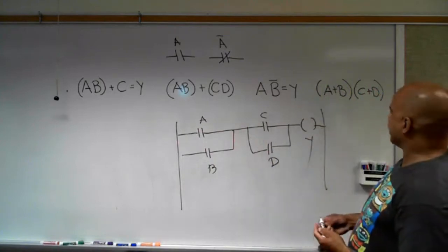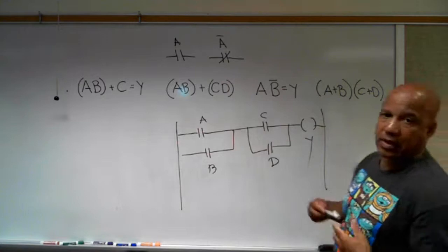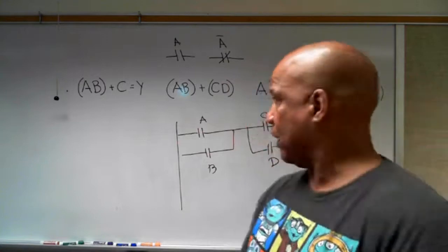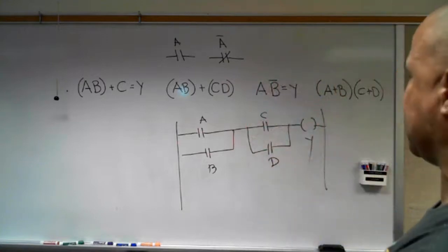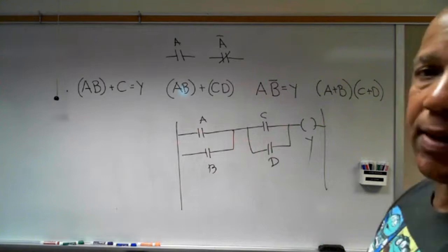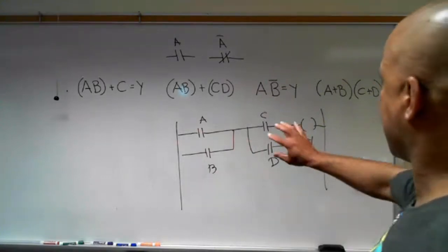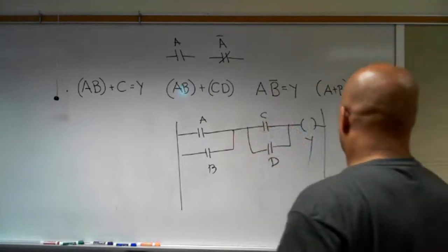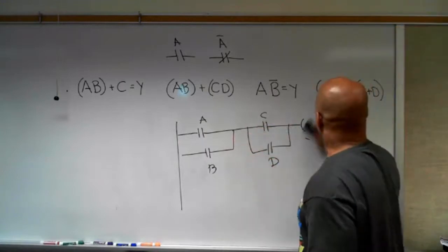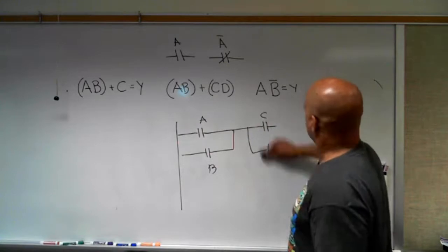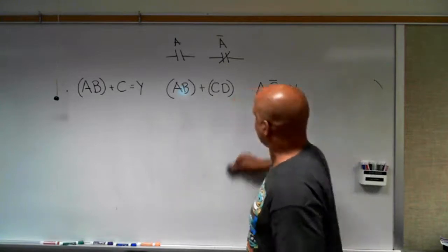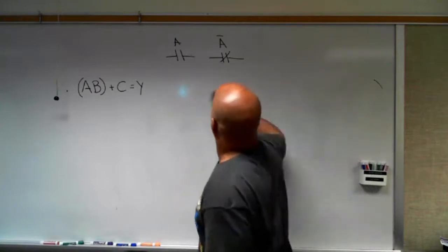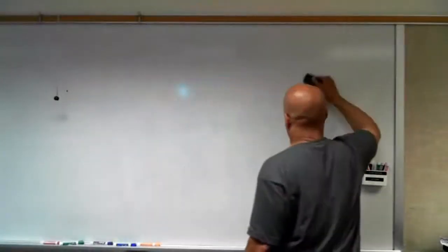So there's some quick practice on how you would implement AND, OR, or NOT logic using relay contacts. You'll see today when we get into the programming that the kind of programs you're going to write look really close to this, but the meaning of these symbols will be slightly different, and we'll talk about those. So any questions over anything I just did? I think you should find that to be pretty easy.